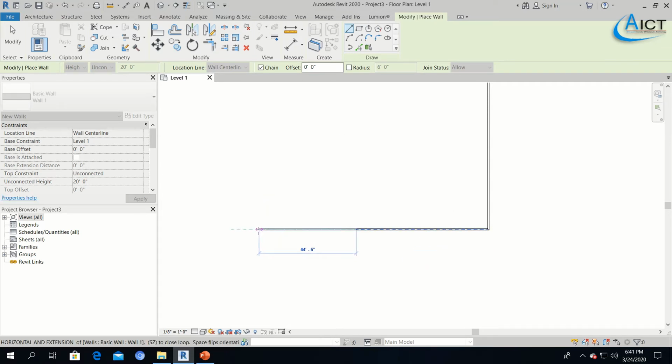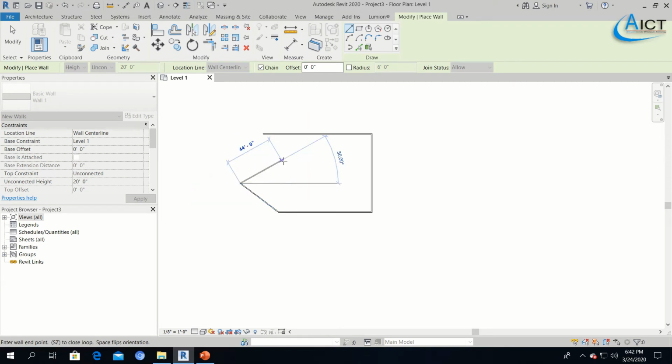For example, again I will tell, if you type just 300, it's going to be feet. If you put double quotation only, it's going to be 300 inches. So by default, that is going to be feet. So now I put double quotation, so it's going to be 300 inches. So like that, you can specify your specific lengths also.